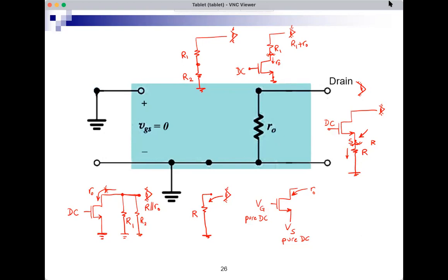So what is the answer? Well, the rule doesn't apply, so we'll not use it. If I want to find this, it's like calculating a new quantity. I will do a full small signal analysis, and then I will get the answer. I don't have a rule for that so far. So make sure that if you're applying a certain rule, you're satisfying its conditions.